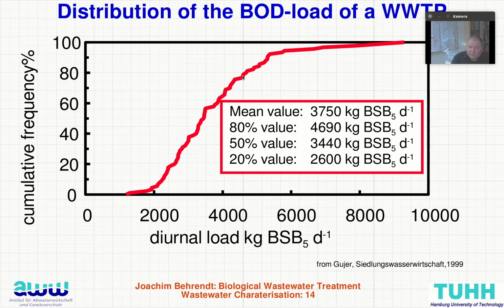Or the 80% value: in 80% of the cases, the BOD load is smaller than 4,690 kilograms BOD.